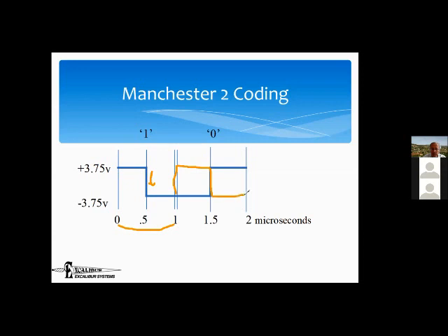and onwards. So the middle of each bit always is changing direction. Between bits, sometimes it will change direction, right? So generally speaking, if you have the same bit value twice in a row, then it's going to have to change direction both in the middle and in between. And if you have different values, then it won't. Okay, so that's the way you can distinguish between a 1 and a 0.